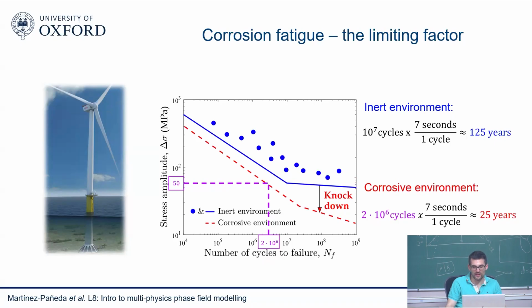And this is quite complicated because, first, SN curves are not suitable when you deal with corrosion. When you deal with corrosion, SN curves have a number of assumptions embedded. The first one is that you apply superposition, right? We said we have loads coming from the sea current, from the sea waves, from the wind, so we add them all together into this number.